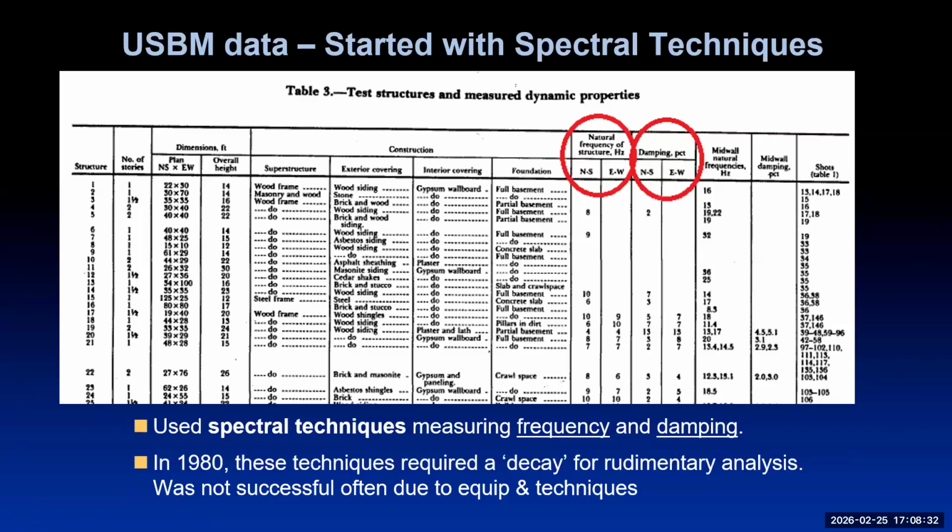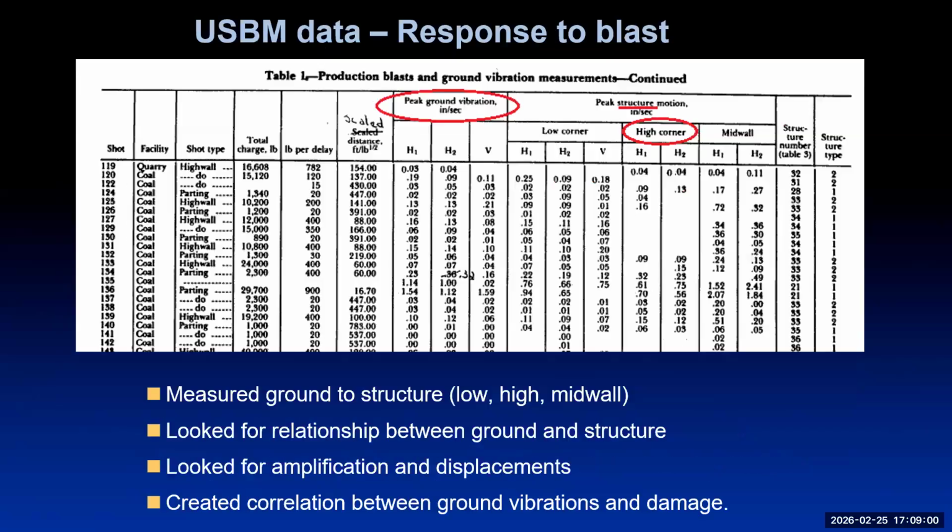So again, going back to everything Dr. Geary just said about measuring at low amplitude, that allows for a statistically valid measure of a structure's response, understanding its resonance conditions. And those resonance conditions are the things that can amplify during dynamic energy. So if you're only measuring at very high amplitude, you get messy results. If you measure at low amplitude, you get very clear, accurate, repeatable results that can be used to extrapolate up to the risk criteria.